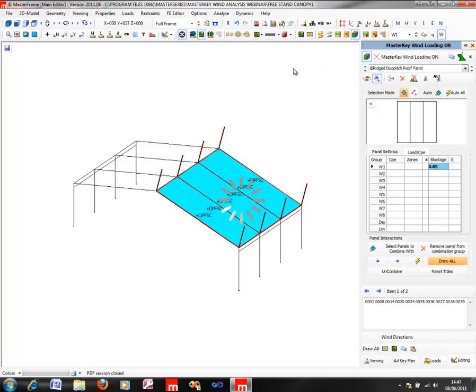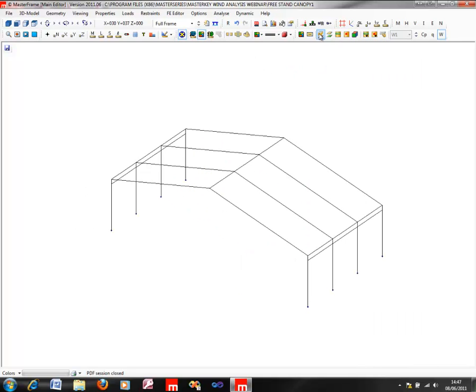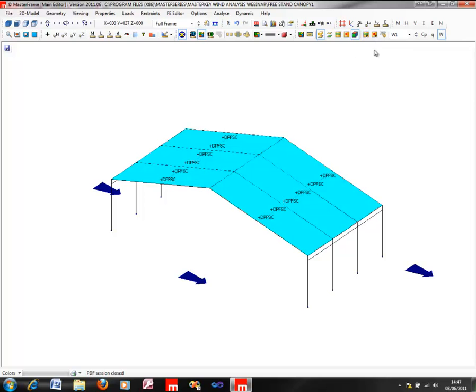We can see how that comes into play by looking at the values. It would have been 0.79 previously, now it's 0.114. In actual fact, that blockage ratio probably would need to have been specified on this surface as well as this surface, as they are connected, and the blockage would affect this surface equally as much as this surface.